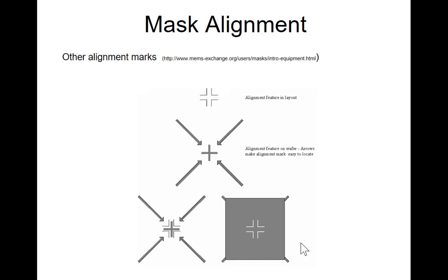Okay, and there are different ways to make sure that you come back to the same location with very, very good accuracy, maybe just in nanometer level accuracy. And if your feature size is only 7 nanometer, then the accuracy control needs to be sub-nanometer. So that causes the equipment to be very expensive.